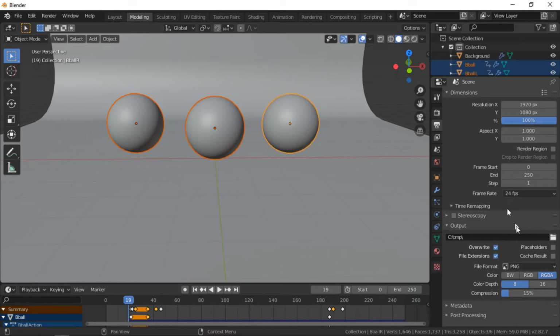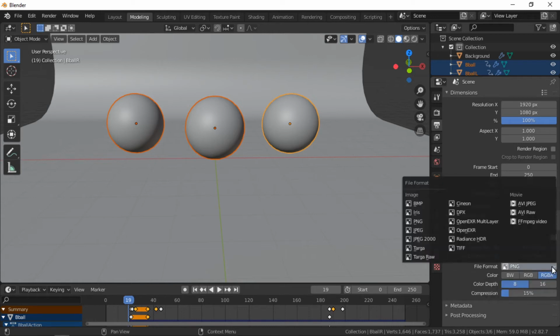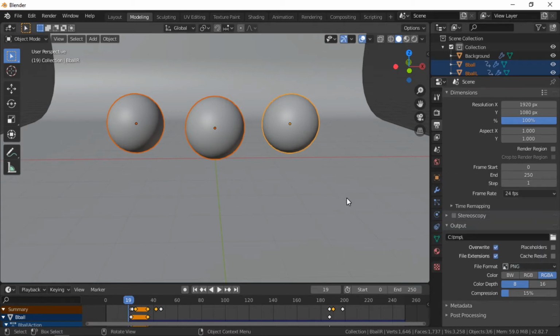When rendering animations, it is recommended to render to a series of image files. The image files can then be compiled into a movie file. A movie file can be used for rendering, but if the rendering process is stopped, it will need to be restarted from the start. When rendering to image files, the rendering can be stopped if needed and restarted from the next image.